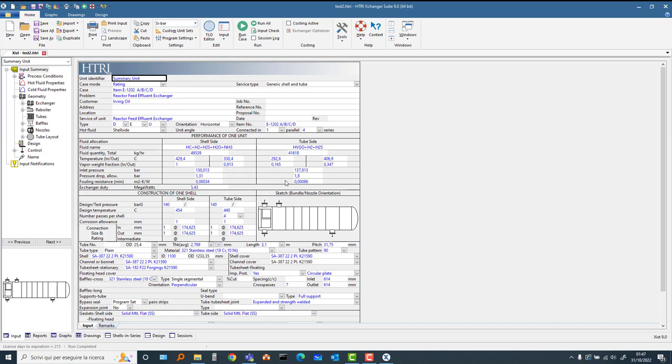On the other end, on the tube side fluid, you have 0.165 at inlet, 0.3407 at outlet, so there is evaporation. There is already at the beginning a certain amount of vapor, but the amount of vapor is increasing due to the heat transfer from the hot side fluid.